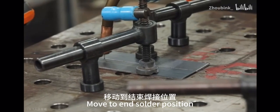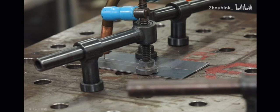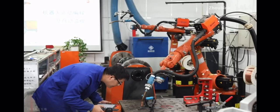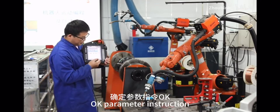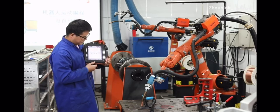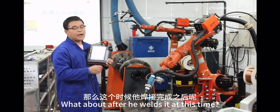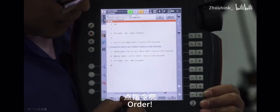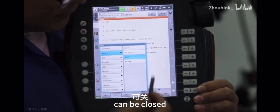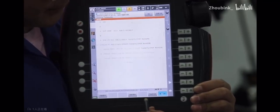Move to an end solder position. Front, rear, left, right, up and down can be adjusted. OK, parameter instruction. What about after he welds it at this time? And give him one more instruction. Tell him to turn off the arc. Arc off command, OK, parameter instruction.